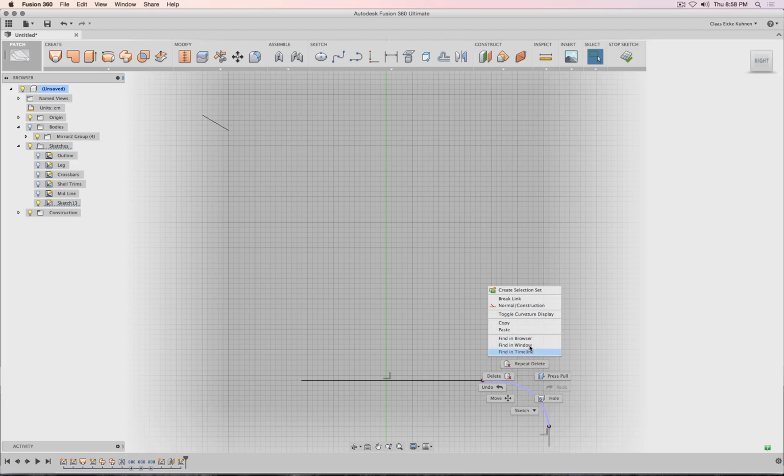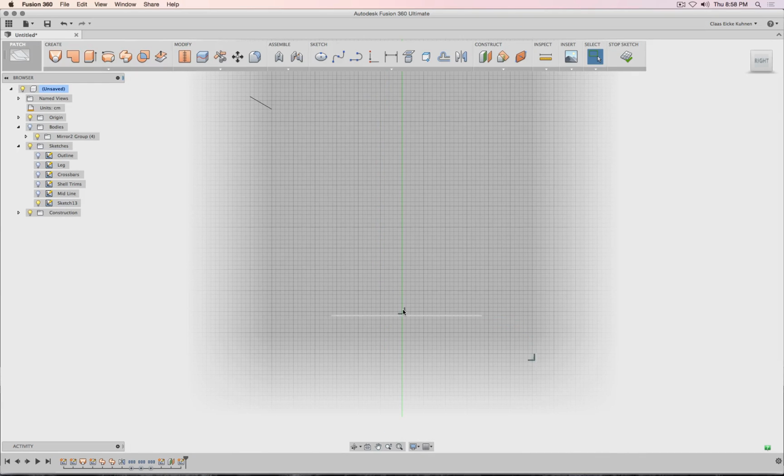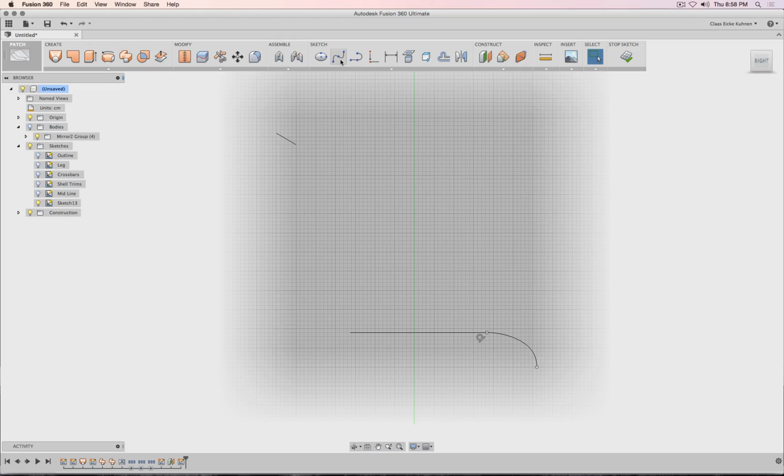So I could, for example, break the link. Let's see if we can actually show the handle. We can't, so there's no show tangent handle or so, which is why from those splines I'm going to delete all the lines, because then you see I patch in a new set of lines. Okay, this one maybe. This line I delete because I don't need it anymore. And here I can click, so I have a position, click and drag out. This line I don't need anymore. So you see I use this basically as a helper.